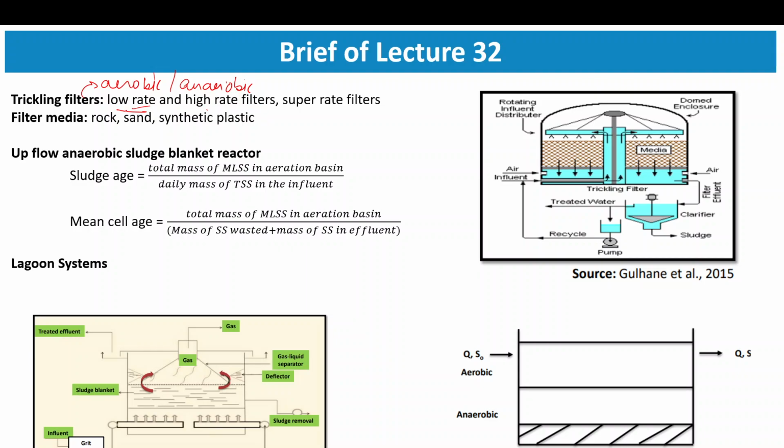As the name suggests, low rate means more time is provided, like the rate of flow is less. So here you get more efficiency for removal, and for high rate, obviously you will get lower efficiency for removal because the amount of time it spends inside the reactor is less.